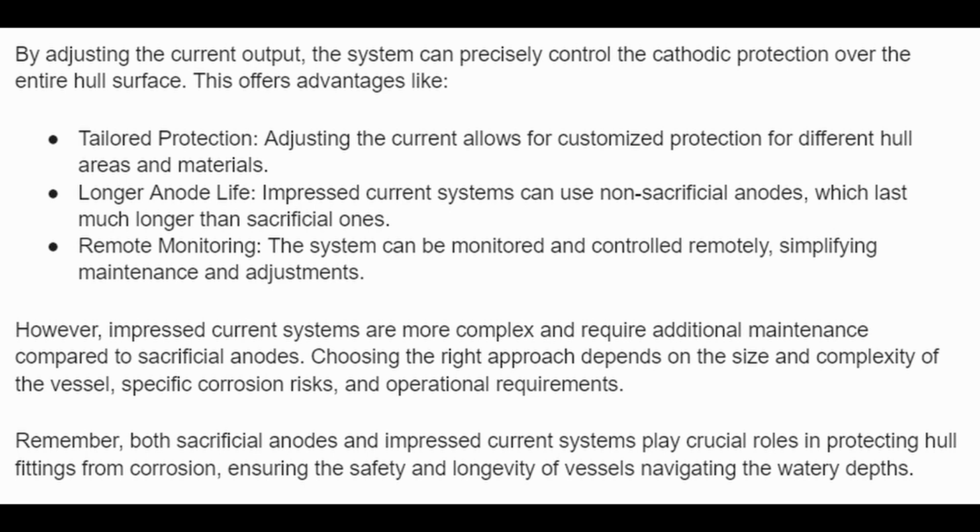This offers advantages like tailored protection. Adjusting the current allows for customized protection for different hull areas and materials. Longer anode life. Impressed current systems can use non-sacrificial anodes which last much longer than sacrificial ones. Remote monitoring. The systems can be monitored and controlled remotely, simplifying maintenance and adjustments.